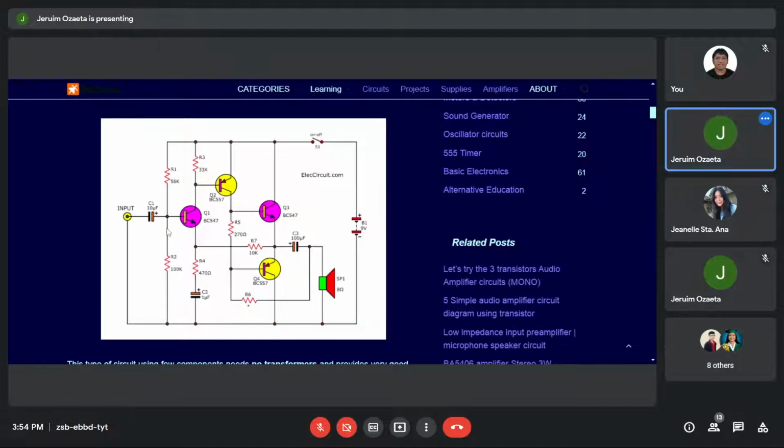And then the output goes to the Q2 through the collector of the Q1, and then Q2 will behave such that it will provide input to Q3 and Q4, which is a push-pull combination. So through R5, Q4 will determine whether it's going to conduct, and right away Q3 will be determined by Q2. Take note that Q2 and Q3 appear to be a Darlington amplifier.